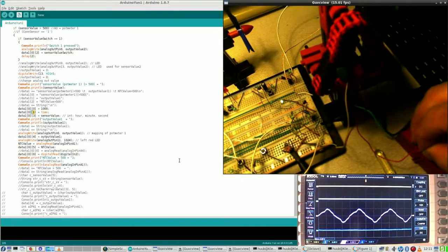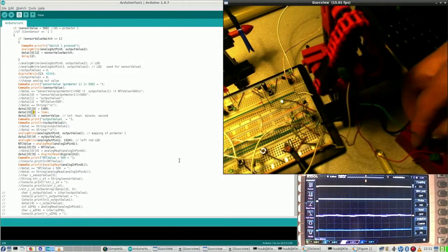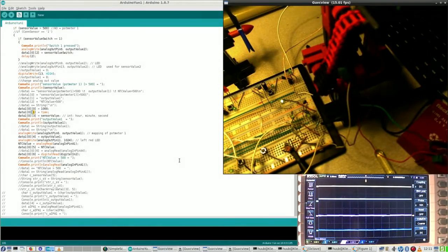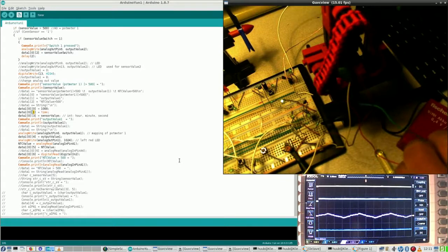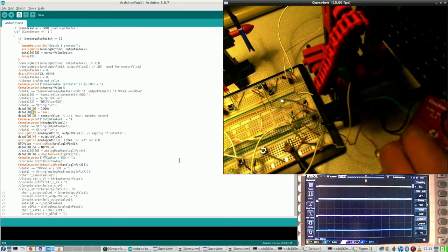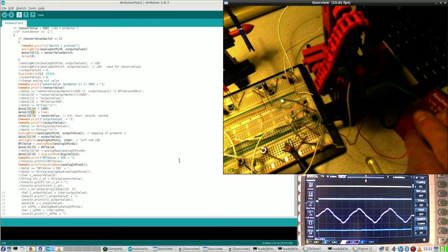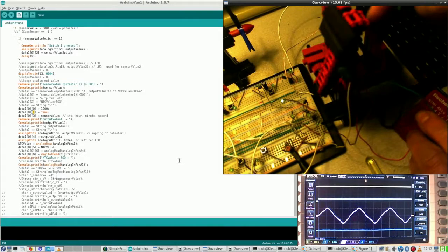Apart from that, right now the voltage looks like some 5 volts. Previously it looked more like 9 volts, which it should be unless this battery is running down fast, which is of course possible, but this is currently the source for the lamp that is burning brightly right now.